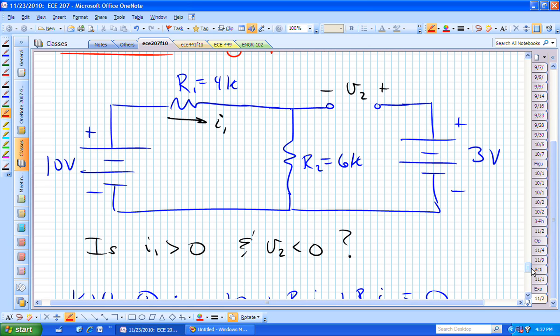Oh, flooded with questions. On the left, in the P material. Sorry, I'm seeing the diagram. And our PN junction is right in the middle. Yes? So doesn't it mean if we got negative voltage that it's actually flipped with what we want if you guys are showing that since we got a negative? So now V2, as we've sketched it, is negative, which means what? It just means that the left node that is connected to our diode is more positive than the right node. And that's what would indicate that we had a reverse biased diode.